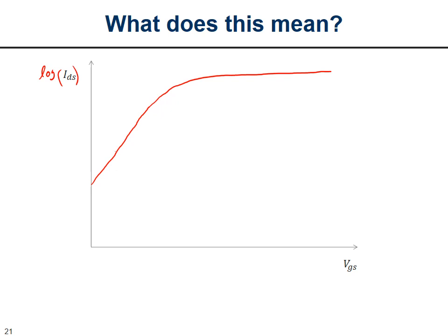And we can say that, well, if this is an exponential on a log plot, it should be linear. We'll have some sort of slope here. Let's call this S, in this case for n equals 1.4 for a MOSFET. We say that S is the subthreshold slope. And just beware, we call it a slope. Usually slope is dy over dx. In this case, our slope is dx over dy, so it's a little bit different units than you're used to. Just be aware of this. People get messed up in assignments and exams oftentimes about this.